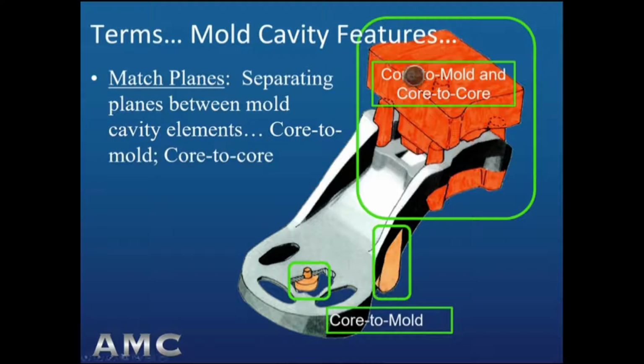In the upper right is an assembly of resin shell cores, which are very accurate, making the datums and the hole positions of an axle seat assembly for this suspension component for a Class 8 truck accurate enough to not be machined.